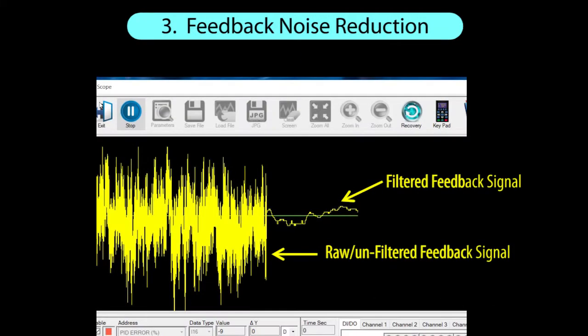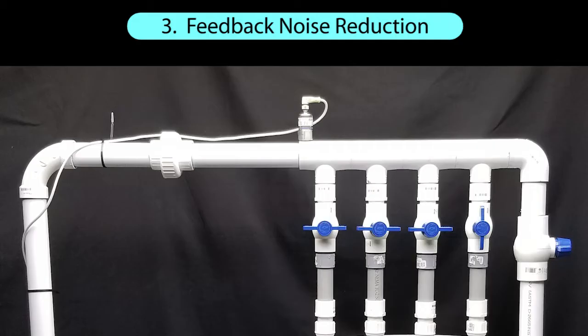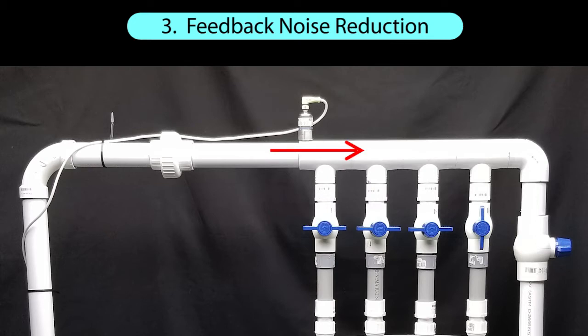We saw in one of the earlier videos that the feedback signal in our demo had a lot of noise on it. Why was that? There was a whole bunch of noise reduction techniques mentioned in Chapter 2 of the user manual, but none of those were the problem here. The problem was system design. If you look at this, the feedback sensor is located right next to a junction that was generating turbulence. It's also in the main flow of the water.